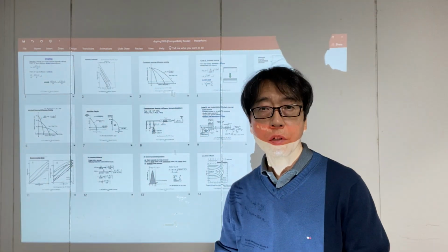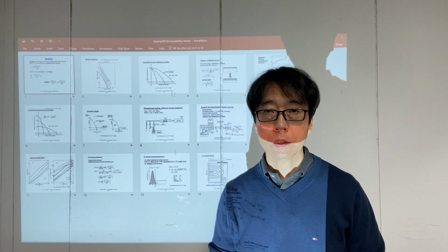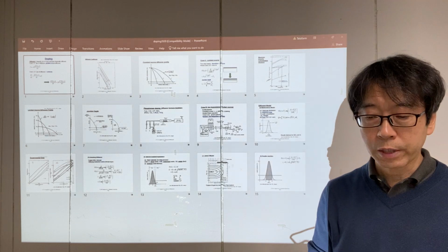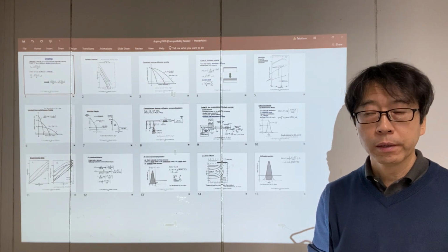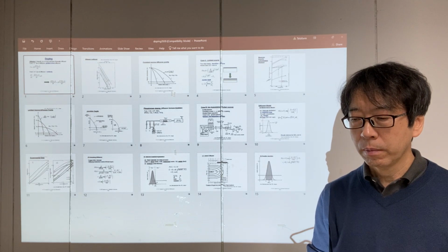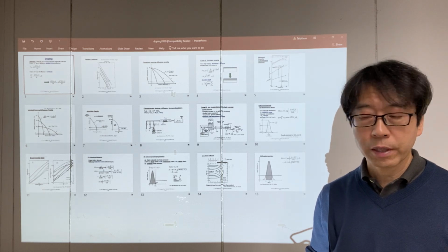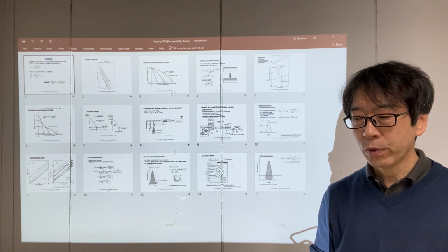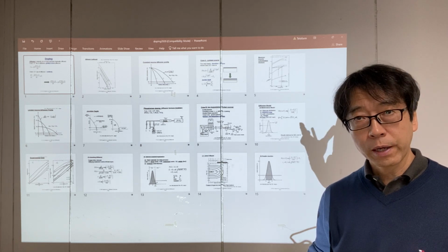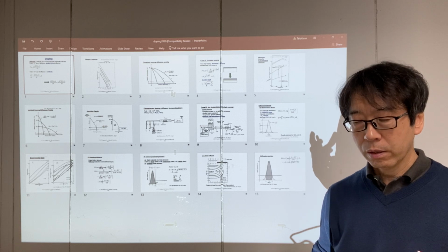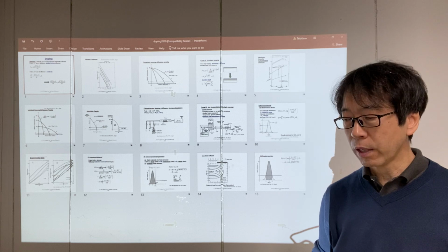Doping is an important process to control the electrical characteristics of a semiconductor by adding impurities. Later on, you see that you can also control the mechanical properties, and most importantly, the etching characteristics against some kind of etchant. In other words, if you have a doped volume, doped area, or doped shape on top of the wafer, you can leave such an area from the etching. You can protect such an area from the etching.